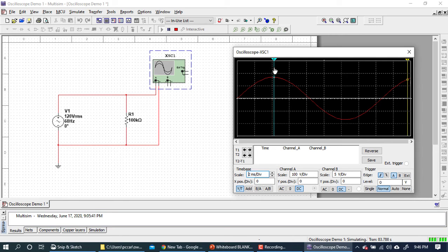And if you want to convert that to a percentage, you can. But what that says is it's 1 times the maximum voltage of that particular waveform. In our case, the maximum voltage of this waveform is 169. So at 90 degrees, the voltage is 169. It's 1, or 100%. Okay? Let's move on.